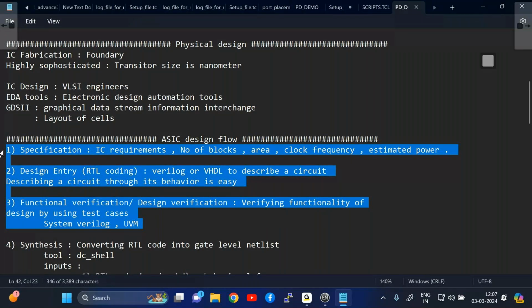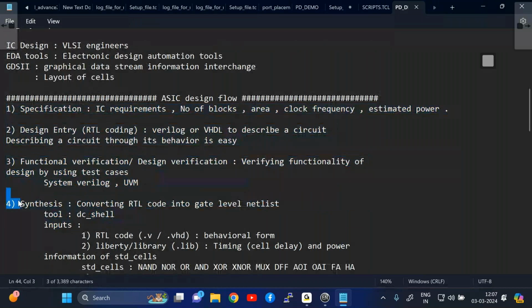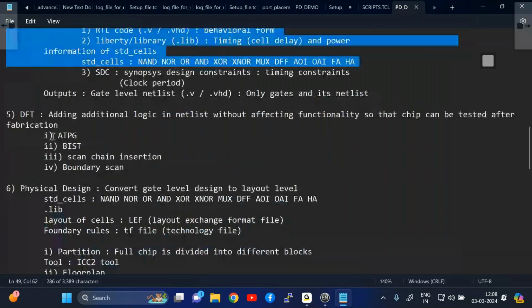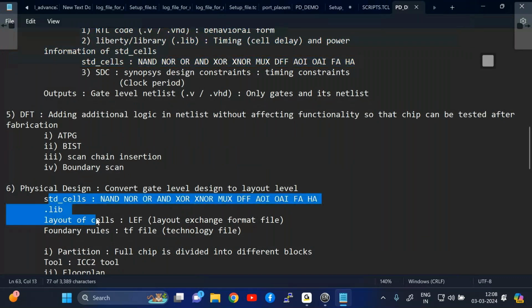After doing synthesis, if they release it, then it is called firm IP. It means they are already mapped to the cells. They cannot change the functionality now. At a bigger level, they can change one or two cells, but the functionality cannot be changed. At the RTL level, functionality can be changed. But when it comes to physical design, if you get the layout, then it is a hard IP. We cannot make any changes inside that. That is called IP or macros.